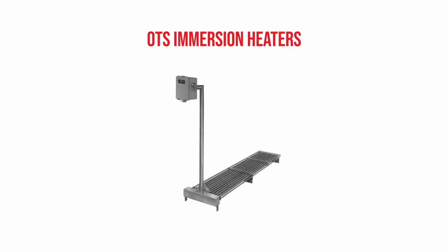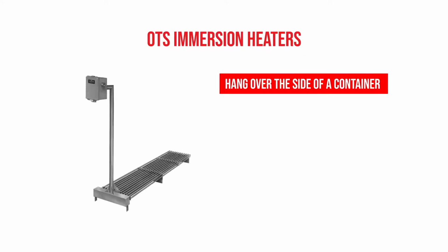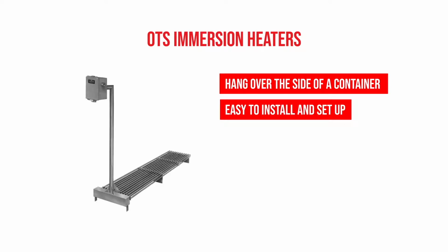The first type is an over-the-side heater. The second type is a flanged immersion heater, and the third type is a screw plug heater. Over-the-side heaters literally hang over the side and can be immersed in a liquid like waters or plating materials, and they can keep that whole tank well warm. It's a very easy application to do and very easy to install. They typically can be very tall and very long because the depth of the tank can be longer, but the heat never starts till the very end of the heater.